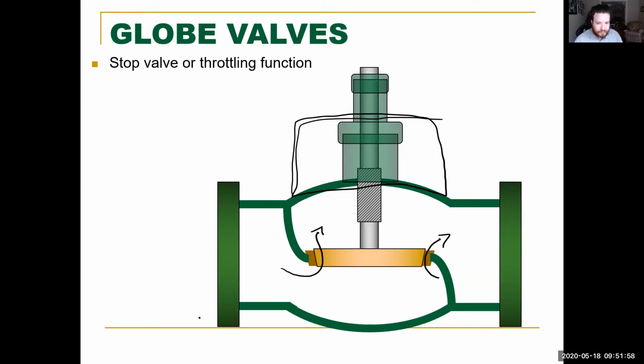And what you're exposing is the seat on either side. If you're not getting as much sealant, you can just come in there with a file, or they make specialty grinding pieces that will grind this down ever so slightly and make a new mating surface.